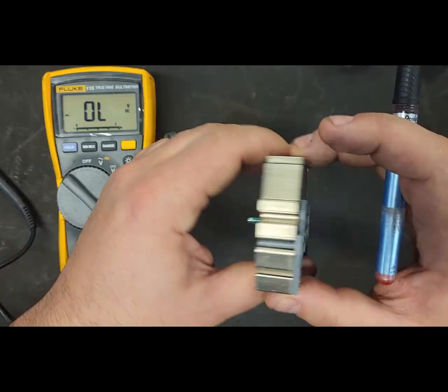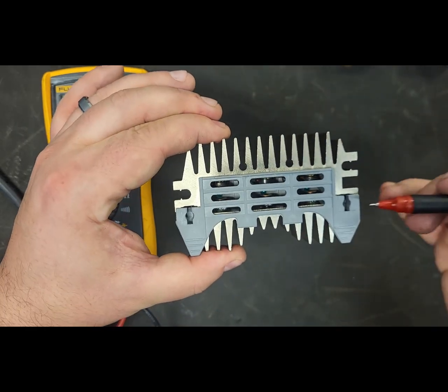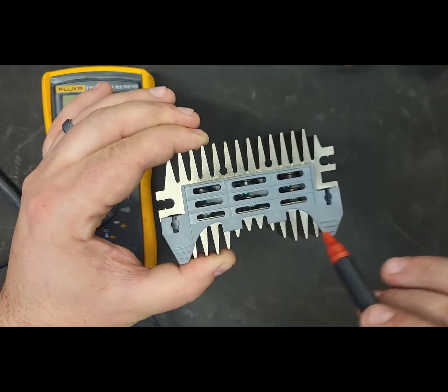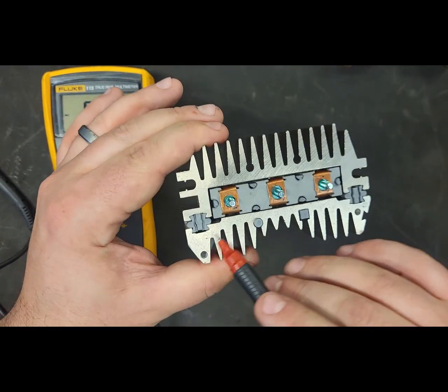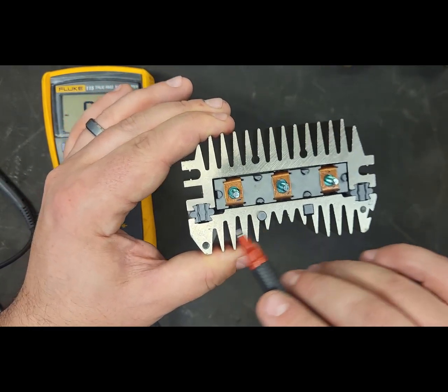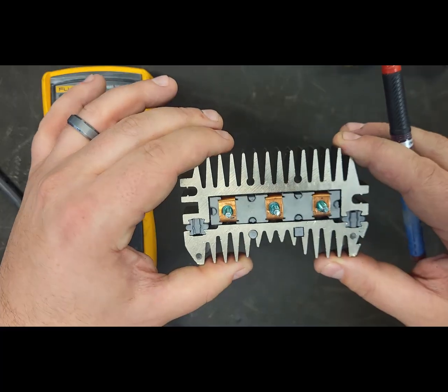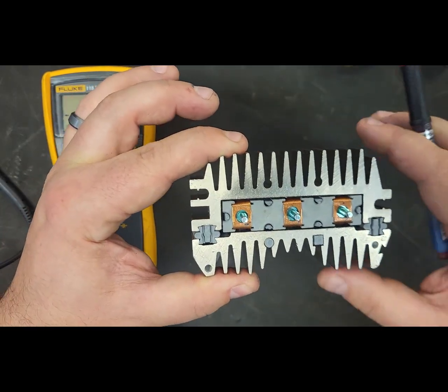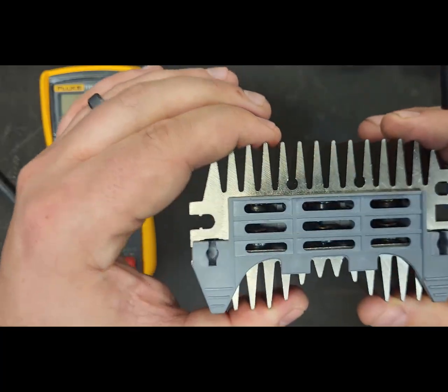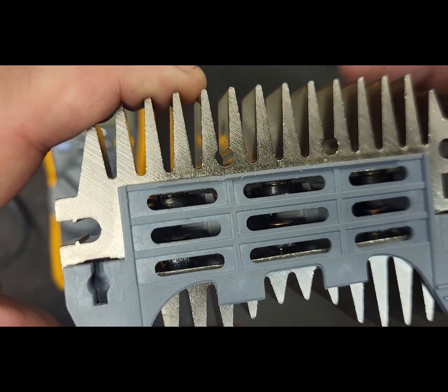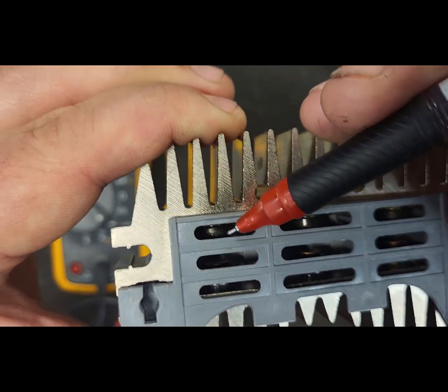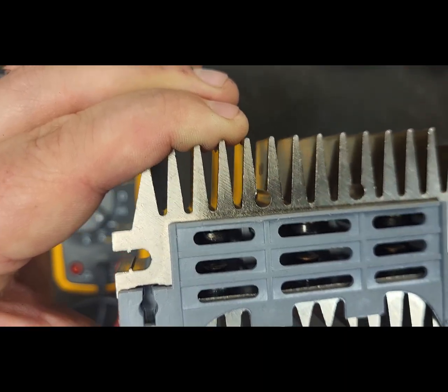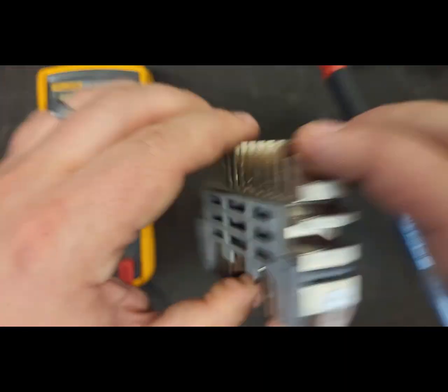So if I look at the back side of this rectifier bridge, whatever side has the plastic sheeting at the 2 bolt holes, that's going to be my positive half. That's the half that's isolated from my case ground. The other half up here, these bolt holes will go straight down through to my case. If I look inside, those are my diodes inside, those little black bits. So I've got one there, one there, one there, there, and there. There's my 6 diodes hiding inside.